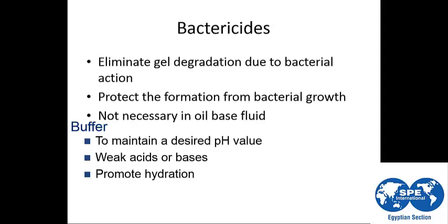So the bacteria result in H2S inside the reservoir, and H2S is very harmful in terms of corrosion. So it is also important to use the bactericide or biocide to prevent pumping bacteria that create H2S inside the reservoir.